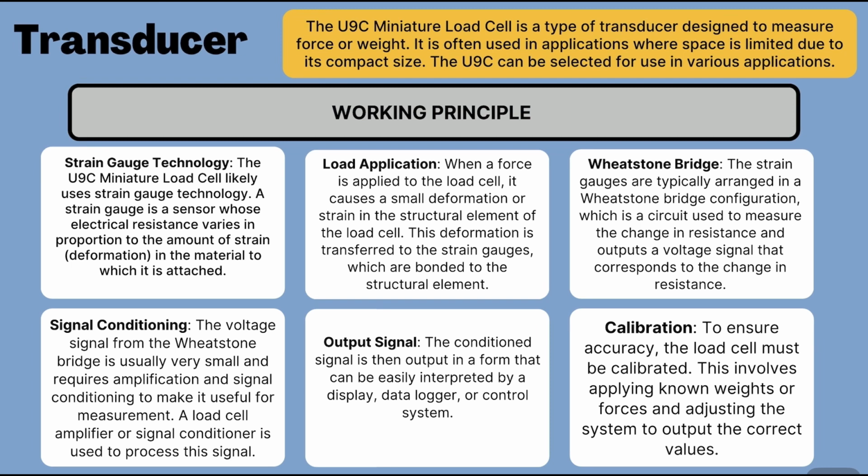And how do we detect the force, you may ask? The force will be detected by the deformation, which I just said. When the force is applied, there will be deformation that acts upon the material, which will change the resistance of the strain gauge and will affect the output. And the transducer uses a Wheatstone bridge alignment or circuit design, so that the configuration will be able to measure resistance throughout the material, and it is much more accurate.